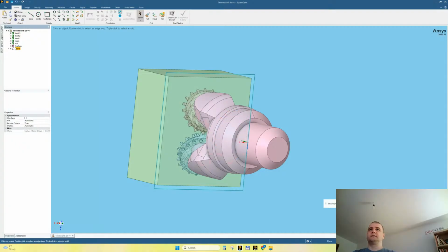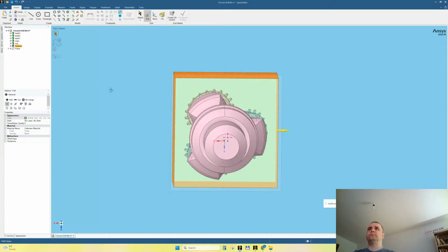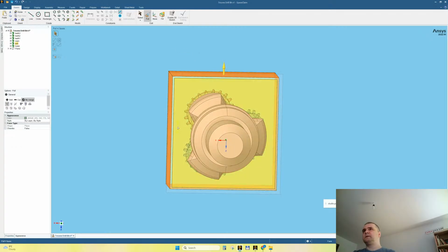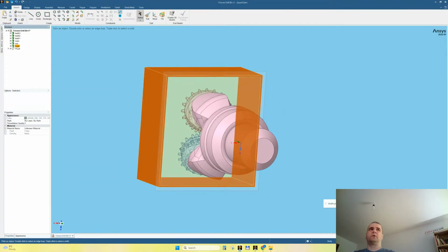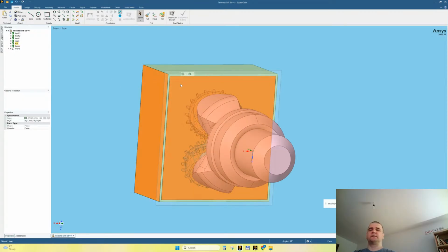All right, and this, I would like to pull it out for a little, just a little, you know. Let's see how much. Something like this. This will act maybe as a holder or fixture. You'll see when we go in ANSYS Workbench. Fixture or frame. I will call it frame because we might need this to define as having a bonded interaction with this part.